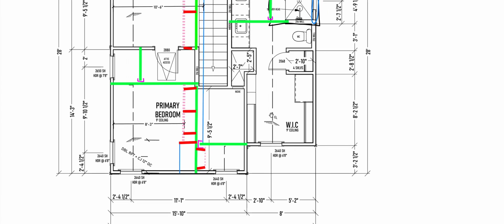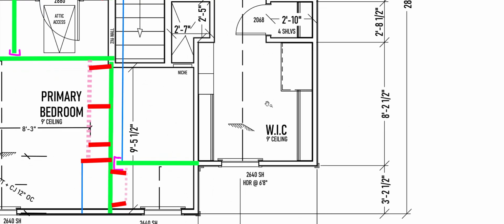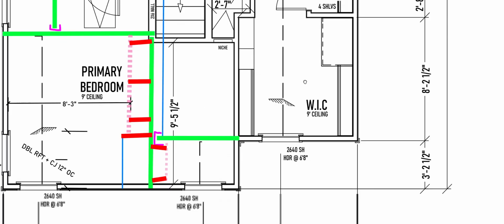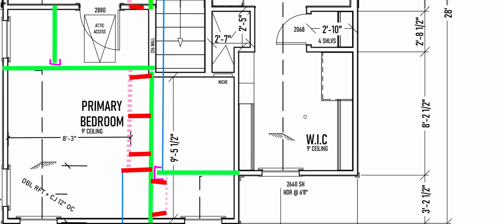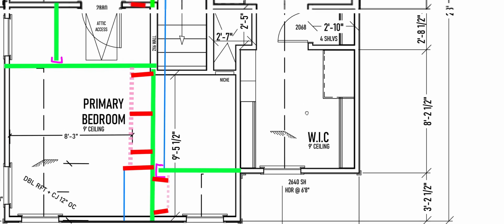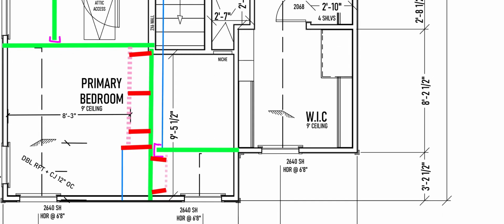Now, on this right side, what do we have going on here? We need to recalculate, because we have a new wall height and a different ridge height. We have to recalculate our HC over HR here. Because of the proportionality and similar triangles, I'm going to see this distance and this distance on the plan.